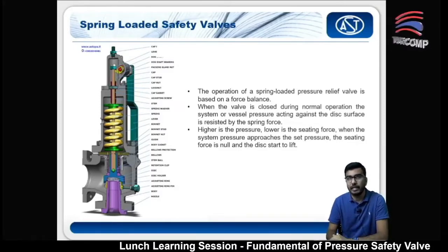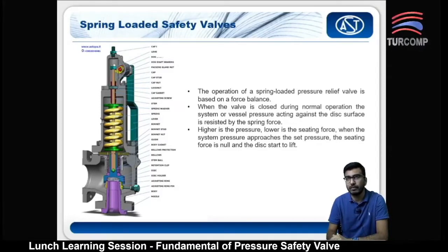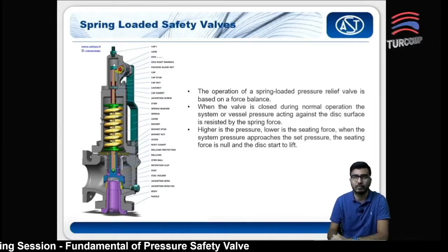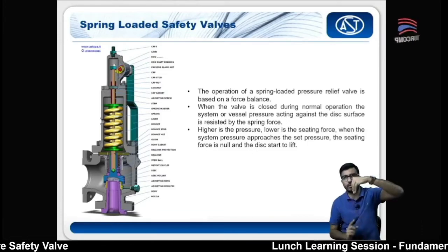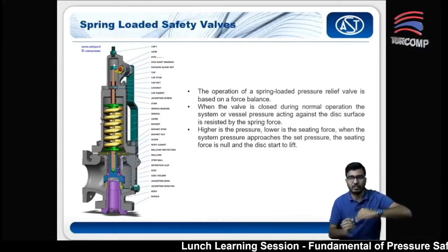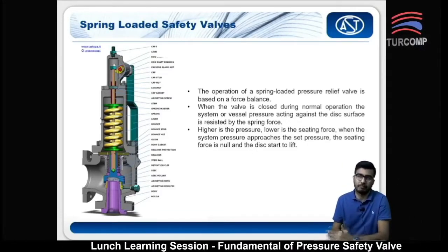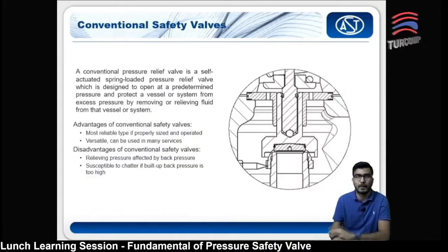So the higher the pressure, the lower the seating force. When the system pressure approaches the set pressure, the seating force is null and the disc starts to lift. When you have more pressure from the bottom, you will actually push the spring up. This is the basic principle.